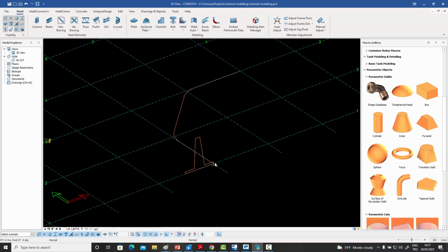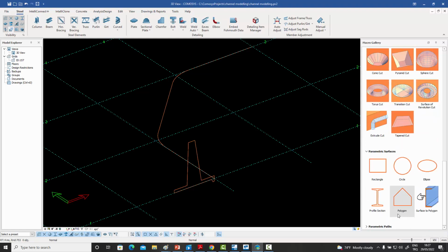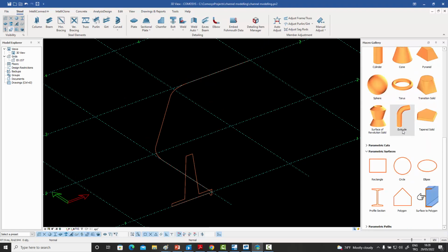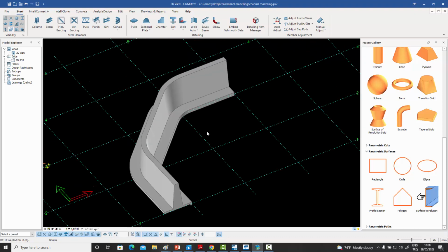So you can have, for example, retaining walls with this kind of a cross section, or anything else as well. And what you can do is you can create these by using this polygon command, and you can even put holes inside them if you want. But what I'm going to show you over here is that you can use the extrusion feature to select this cross section and select a path. And as you can see, the path is curved. It has chamfers as well. And the moment I do that, a retaining wall is created, extruded along that path. And this kind of capability can then be used to model these complex shapes in concrete.